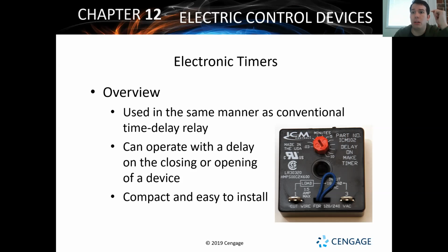Now, here is the biggest thing to help you from shooting yourself in the foot when you're looking at these kinds of timers and delays. Set a timer yourself. Whenever you reset a system, start a clock on your phone, start a stopwatch. If you've got a watch, use the stopwatch on it or on your phone. Don't count on the 1 Mississippi's.